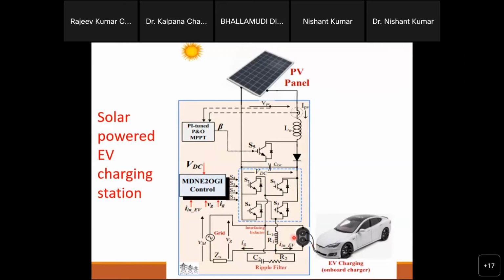The load takes according to its demand, but we have two connections, one is the grid and one is the converter, right? So if your estimation is less, some portion comes from the converter and the rest comes from the grid to fulfill the load demand. In this situation, your grid current will face some harmonics because of the less estimation.